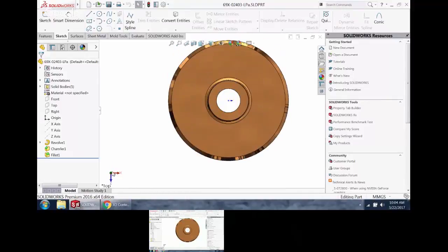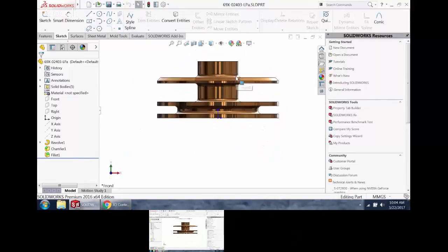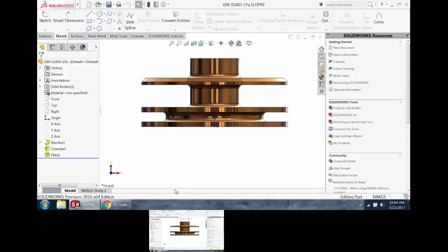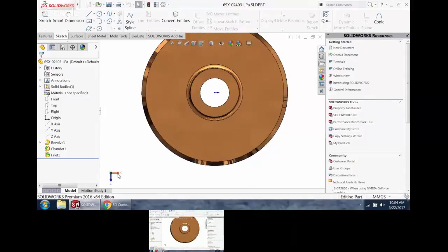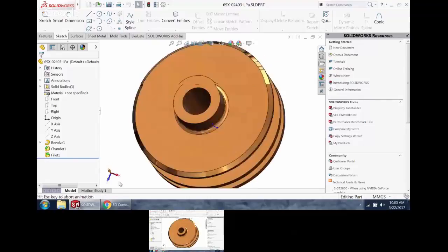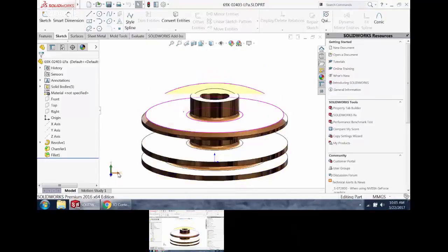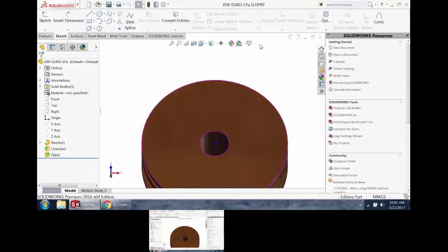All right, what happens if I were to add some keyboard shortcuts with that triad? So just clicking it regular is going towards the axis, so that's a translation type of thing. But if I hold the shift key and I click on this, it'll rotate 90 degrees around that axis. If I hold the Alt key down while I do that, it'll rotate 15 degrees each click. And that's the same as your keyboard arrows. Every time you click one of those, it moves 15 degrees.